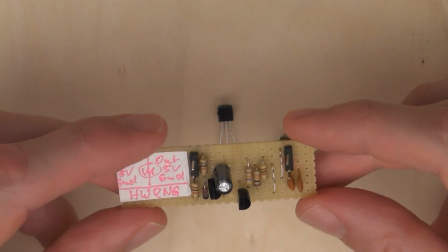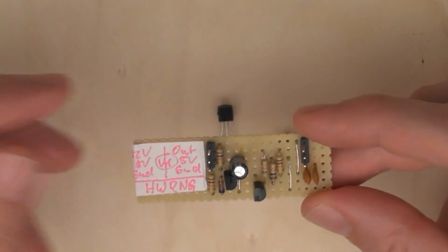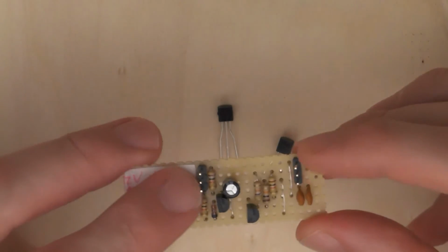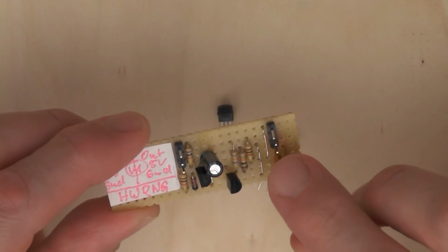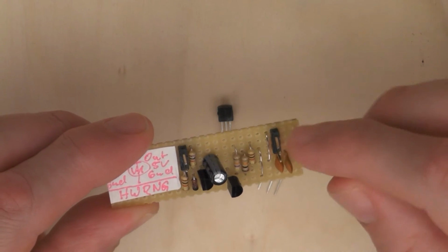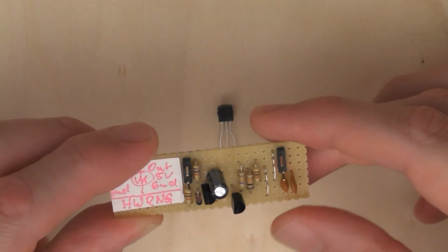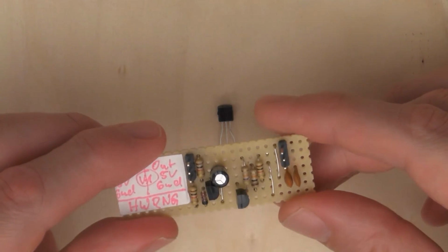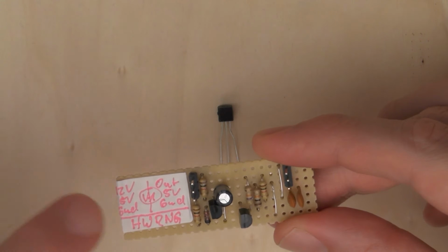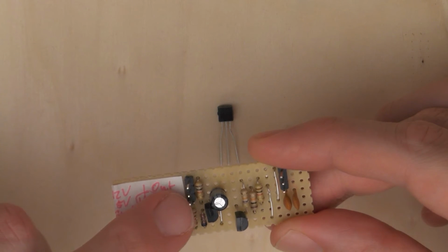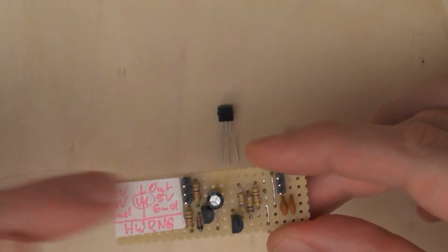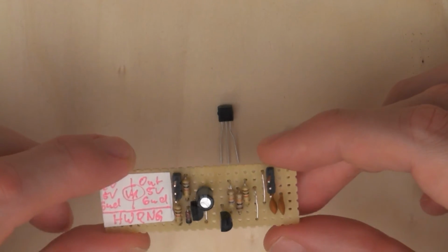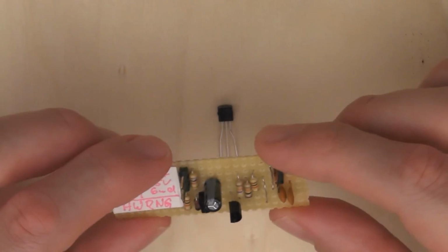It worked. Good. Well, kind of. The connectors, and this is something I've stuck with throughout this entire project: on the right hand side I have ground, 5 volts, and the output, which is basically TTL level analog noise. And on the left hand side, ground, 5 volts, and the 12 volt input, so I can connect some 12 volt source there. Well, for a first try, not too bad.